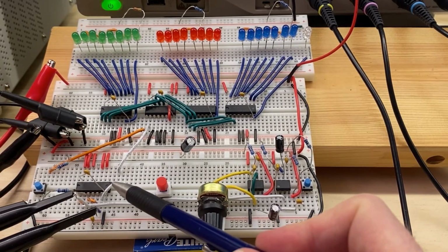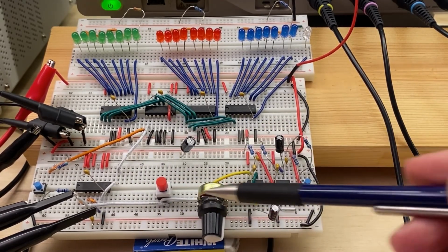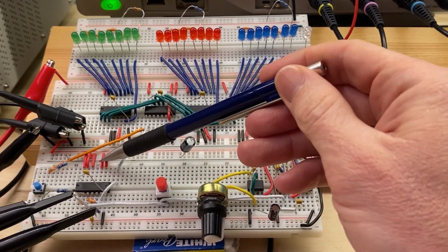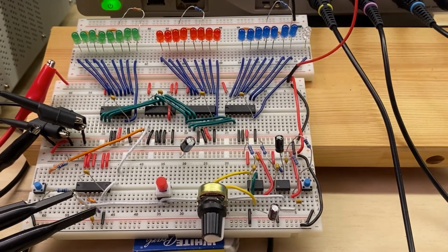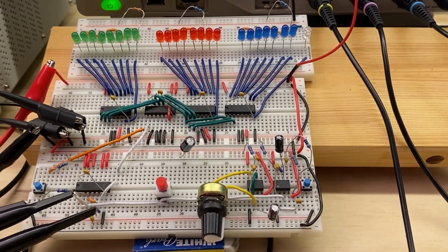And so this is our Schmitt-trigger NAND chip, and I'm just using the two gates below, and the gates on the top here I've all tied to the 5-volt rail, which is how we should normally handle our chips when we have unused gates.